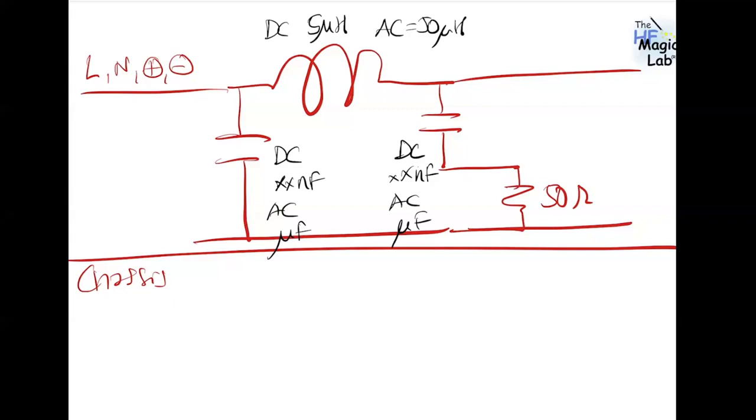So you will have a lot of leakage current, and you will fire the protection system of your installation. Manufacturers solve this circuit in different ways, with a very simple circuit like this one, or with several stages of different inductors and capacitors in parallel, but with the same idea: to offer a known impedance. Additionally, many of them introduce some kind of transient protector, so they are able to protect your system from transients while you are working, especially in power electronics or high inductive loads.